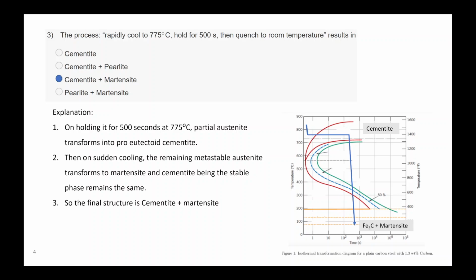No, impact energy is different. Impact toughness is different from the toughness that you measure using the graph. When you measure your tensile graph, you apply the loading rate, and your strain rate is very slow. In case of impact toughness, you apply a strain rate that is very high. So in that case, it depends on the yield strength of the material.